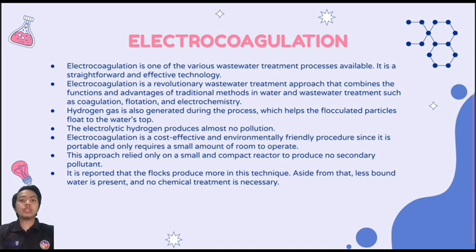Electrocoagulation is a revolutionary wastewater treatment approach that combines the function and advantage of traditional methods in water and wastewater treatment. The hydrogen gas is also generated during the process, which helps the flocculated particles float to the water surface.